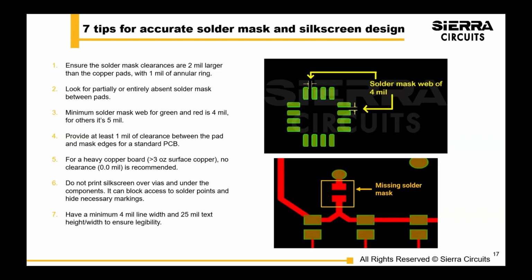Something else off the slide is the color of solder mask does matter, because green versus red versus blue versus black, these all have different DFM guidelines. And so that's something that we've put into our DFM rules when we're checking your data: what's the color of the solder mask, and therefore what are the rules and the spacing that we can have for your design?